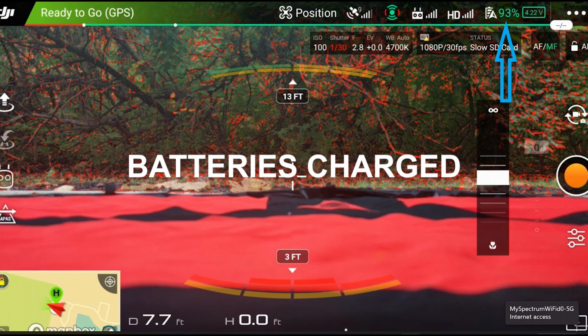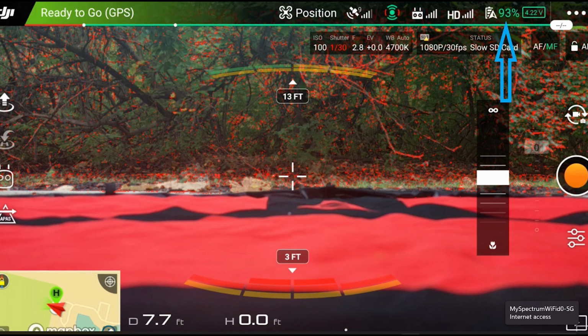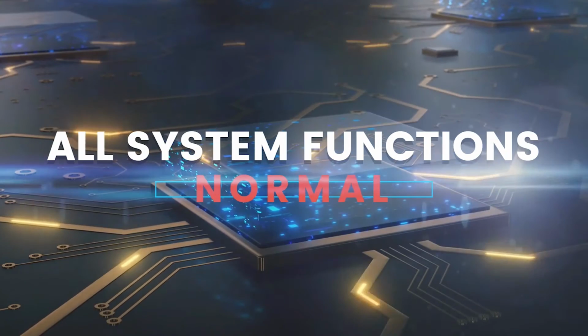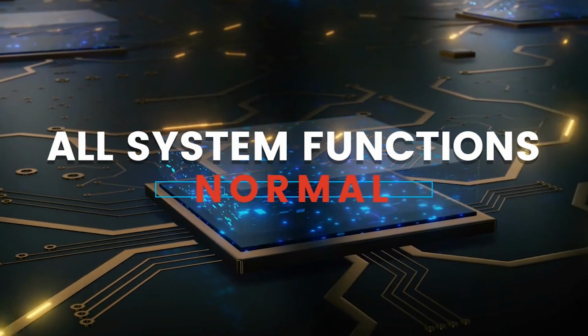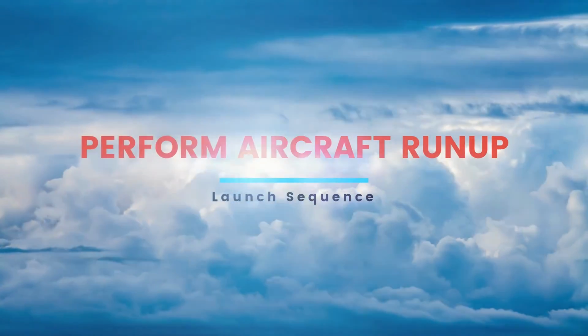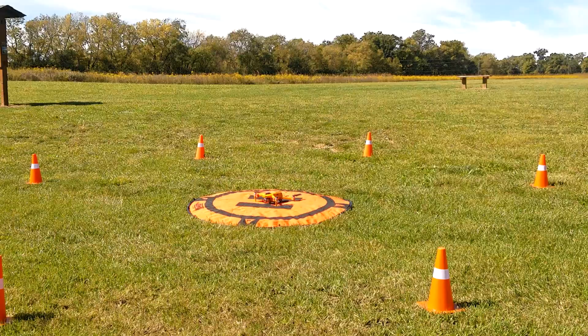Check your power levels and verify that the controller and the aircraft are fully charged. Confirm that it's putting out enough voltage to support your flight. If all of these avionic systems are functioning normally, we can move on to perform the aircraft run-up.